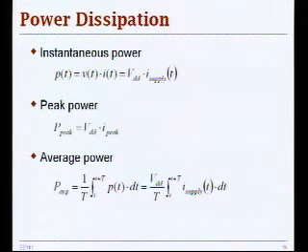And the average power is finally the power metric that is most commonly used in design practice. That is the power that causes you all this heat dissipation and power density problems and all those headaches. So that's basically the average over a period of time of your instantaneous power taken out of the supply voltage.